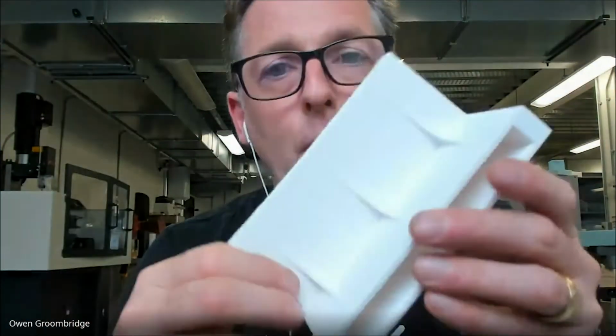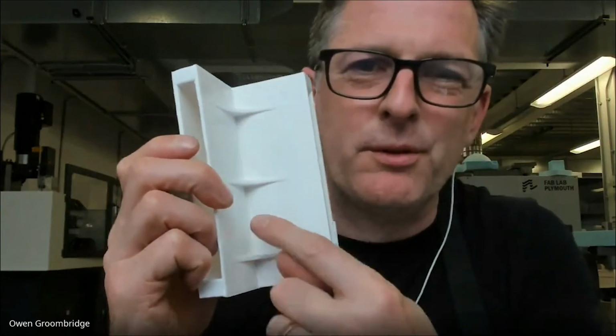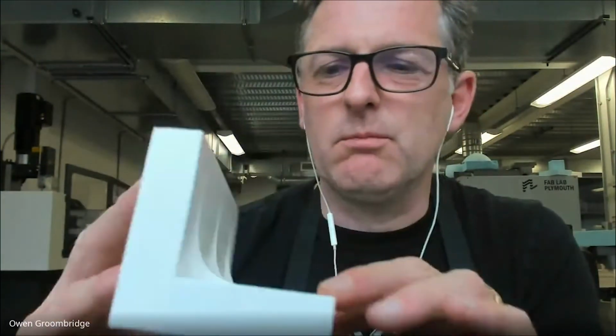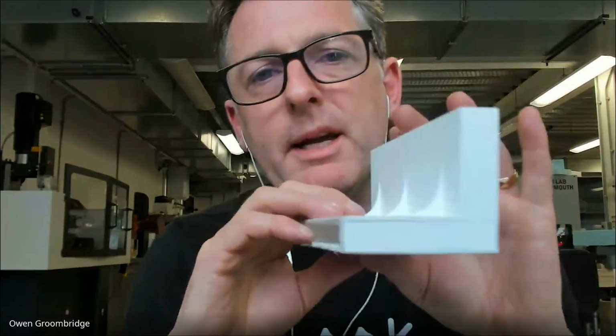Now there are ways of trying to negate that by clever design. By the orientation that you print it out. I could have printed it that way up, but then I would have had some kind of support material issue there. There was all sorts of technical problems. Or when you lay this out in Cura, you could put a really massive brim on it with basically a draft shield. I use draft shields not to keep the draft out or in, just to give it stability. Okay, so you can use Cura for things like that.